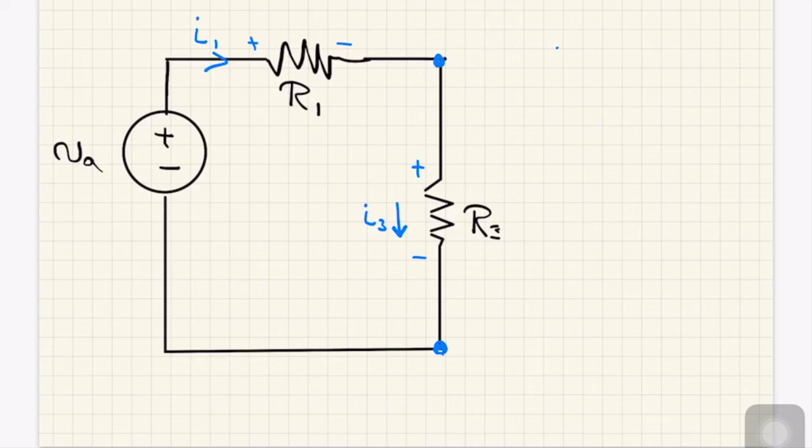There are only two currents there. So we have a current I1 and I3, and I1 is actually equal to I3. There's only really one current. So now we can even adjust this and say this is I3 flowing here, but we have to have agreement in direction, and we do. I3 flowing as it does from left to right up here would flow down through that circuit. So now we can write a Kirchhoff's law equation for this circuit.